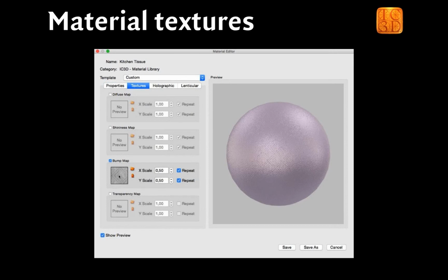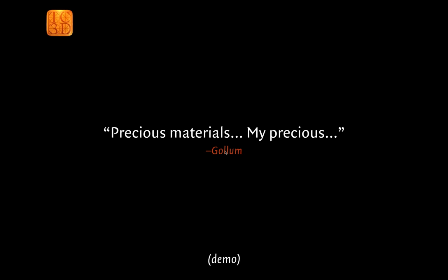You can see this bump map with kind of like this lined, embossed, imprinted, however you want to call it, pattern in there. Well, that's the same pattern that you see on this actual sphere. So that bump map that you have here, together with, if I go back, the bump depth setting that you have in the properties settings, those two work together to create a 3D impression of the surface of that object.